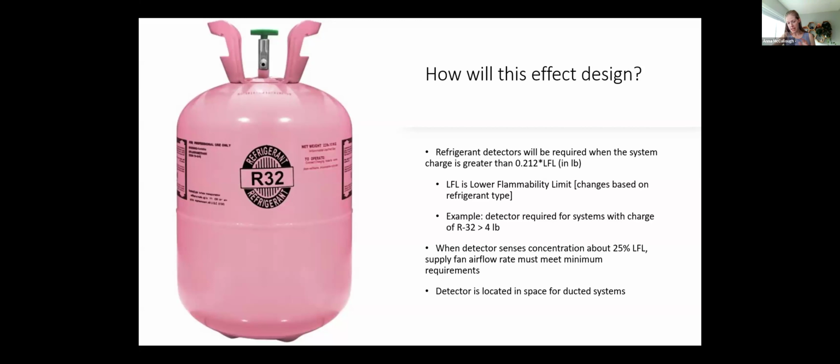Once that equipment is replaced, I think I kind of spoke to this earlier, you cannot charge a system that was designed for A1 with an A2L. It will not work and you'll run into a whole lot of trouble.